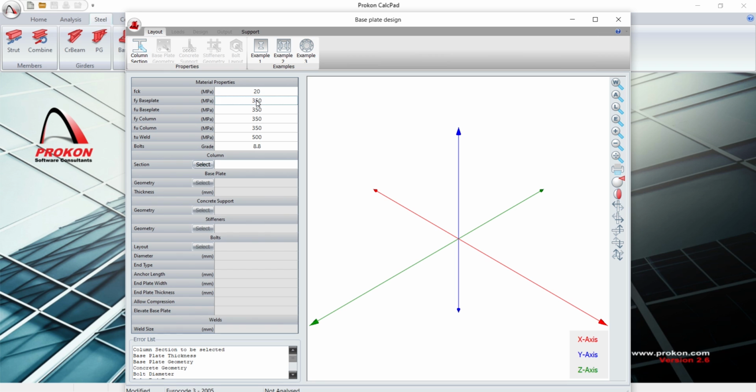For the strength, this is a steel plate. This strength is talking about the strength of the plate. That is the strength of the base plate. Because the base plate is made up of steel, we have 3 categories of steel grade. We have the S275, S355, and S460. In our own case, we use S275.